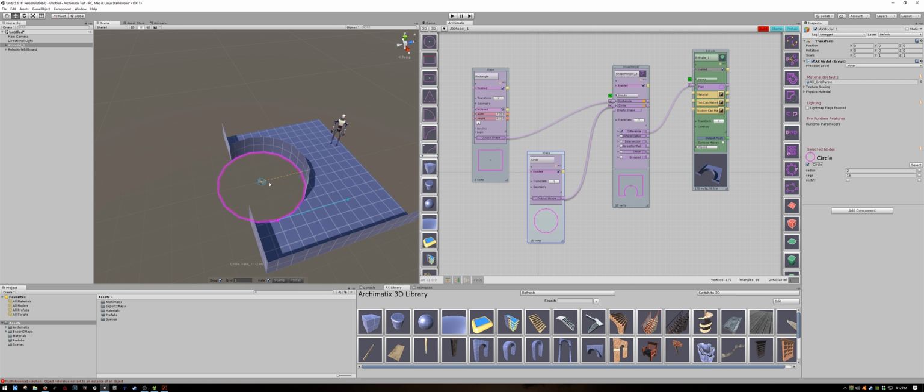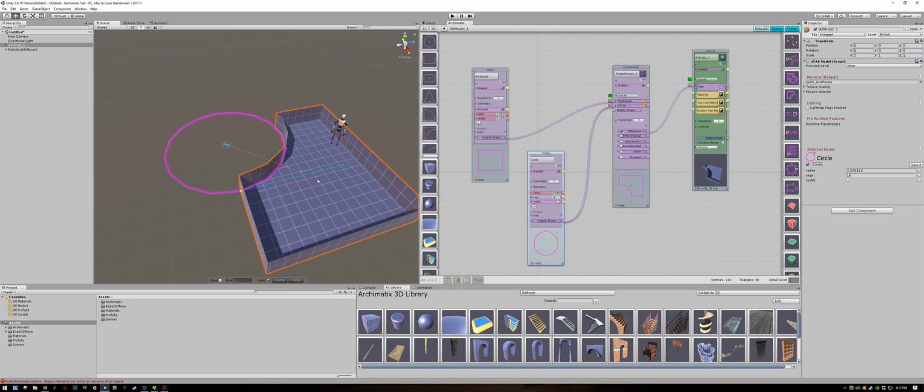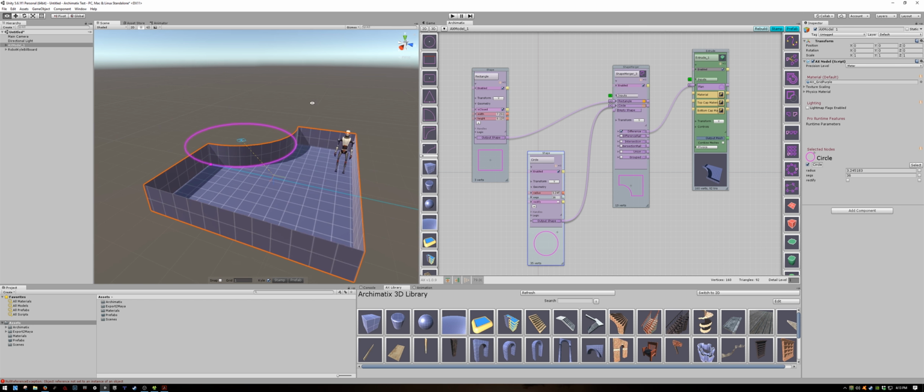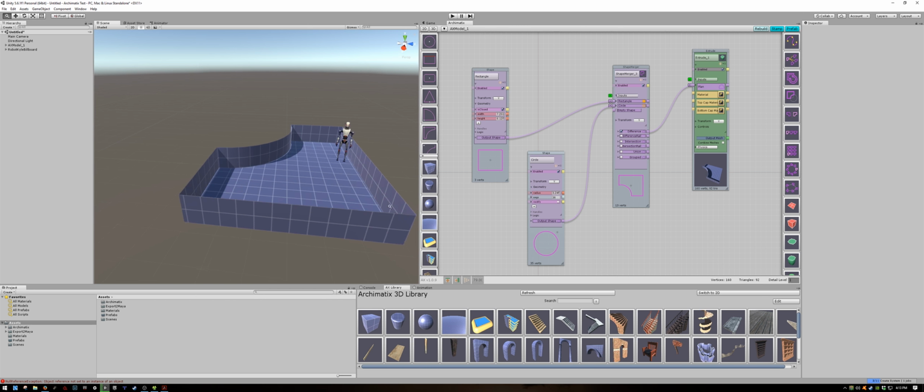And you can see my snapping is still on, it's jumping around. If I unclick my snapping, then I can move it more fluidly. So perhaps somewhere here, I'm going to increase the radius. I'm also going to increase the number of segments to maybe 36. Now it's pretty smooth and looks nice.